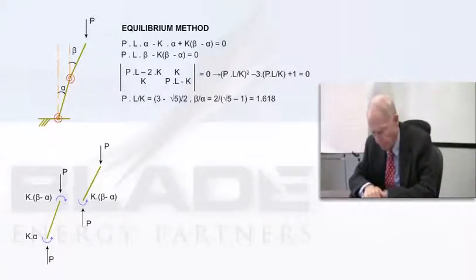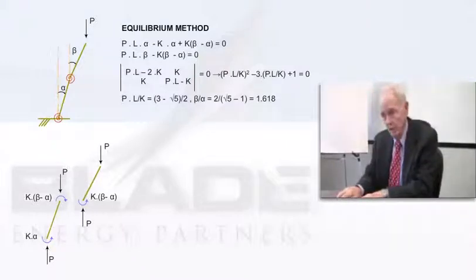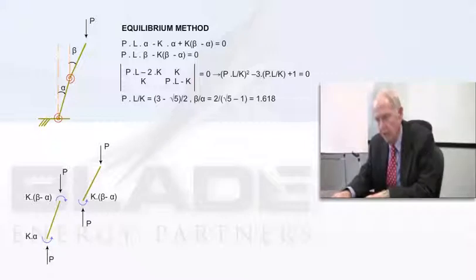And I give the two roots, no, I don't give the two roots. I give the lower root only. And why would you do that? Because you get there first. Because all the stability stuff is based on starting with a low enough load so that you're not buckled, and you increase the load until you get a non-trivial solution.